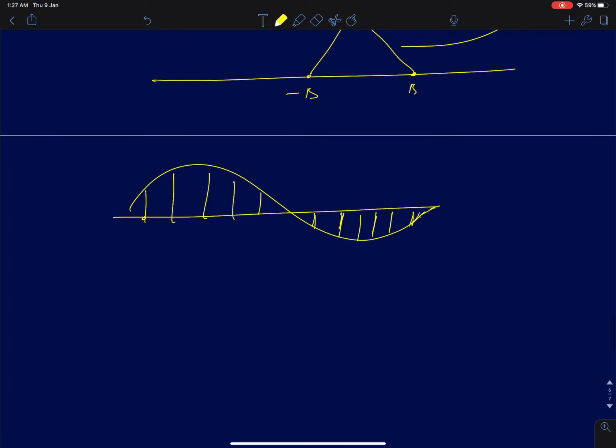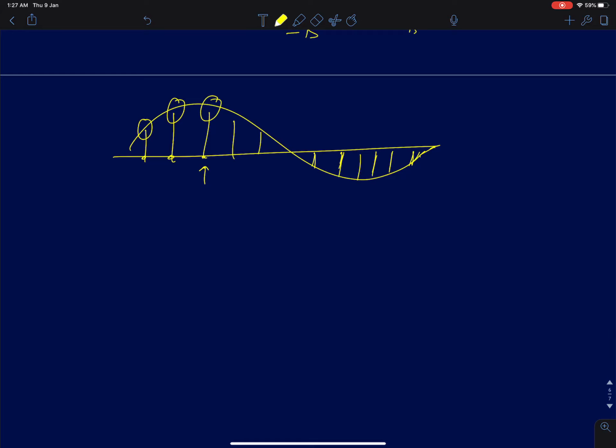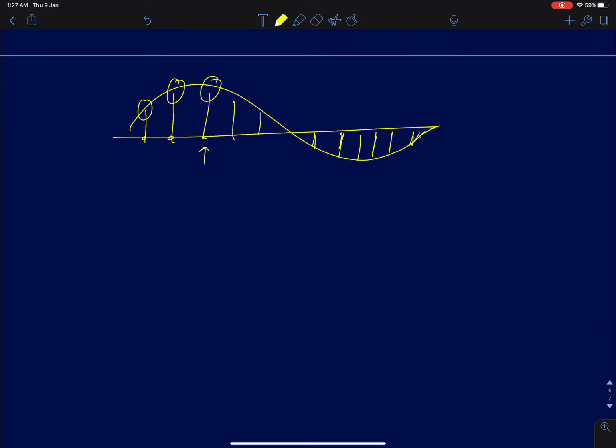Now, of course, we can only store finite samples, which is good. But now the amplitude levels can also have a continuous variation. Anything that is continuous analog can have infinite variations. Because it's continuous, it's a real number, we again want to round it off to the nearest integer possible. So the first step is called sampling. I'm going to discuss what is called analog to digital conversion.